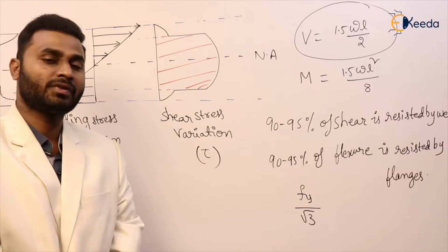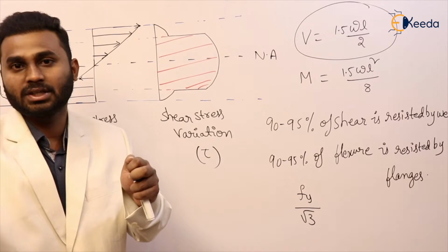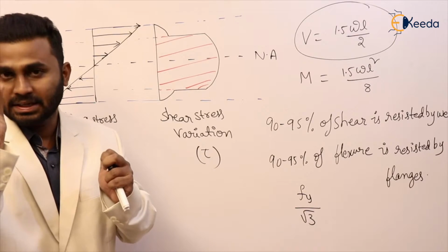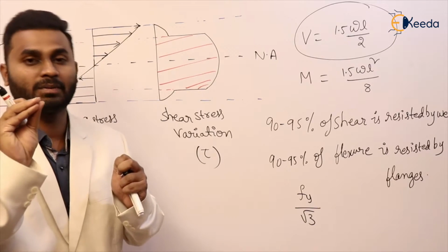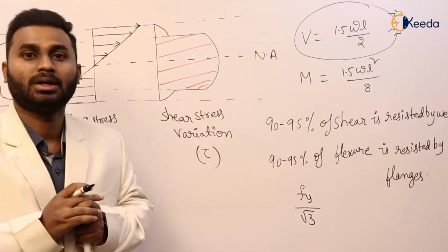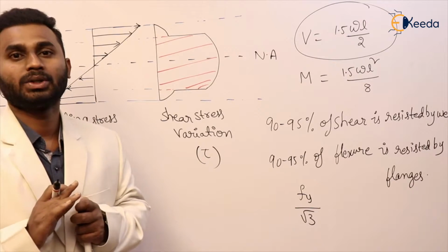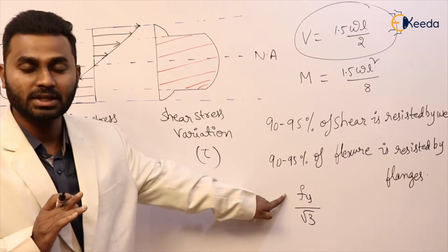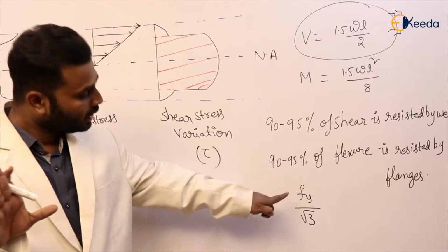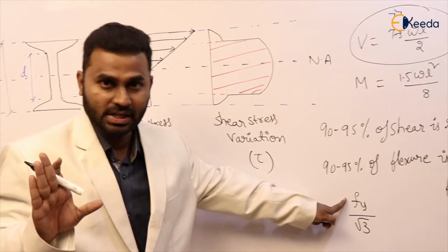In tension members also we have used Fu. Even in connections, in butt weld we have used Fy. So in general, this is not 100%, but you can take it for granted about 90% that the design of connections is mainly governed by rupture failure, and the design of structural steel is governed by yielding. That is why for structural steel we use Fy, and for connections we use Fu, but don't take it for granted. Whenever we are designing in shear, we have to take the yield stress divided by root 3.